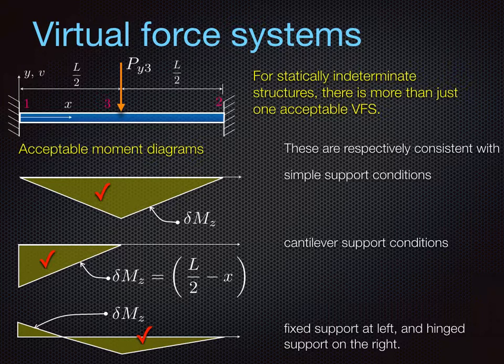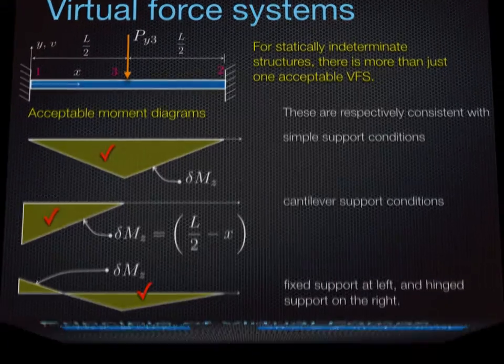This is also an indeterminate structure, but with this virtual force system, we might be able to, for example, compute not only the mid-span deflection in one shot, but also perhaps the unknown moment reaction on the left-hand side. So the principle of virtual forces is quite flexible and will produce very practical solutions for us if we are able to pick a good, useful virtual force system.